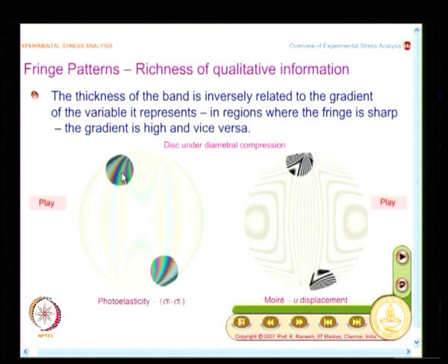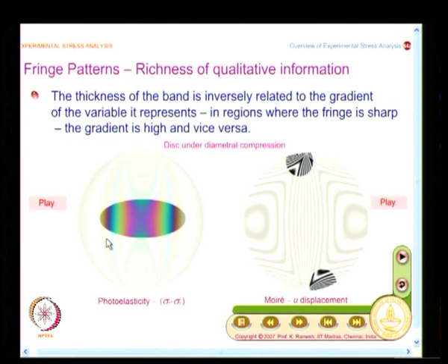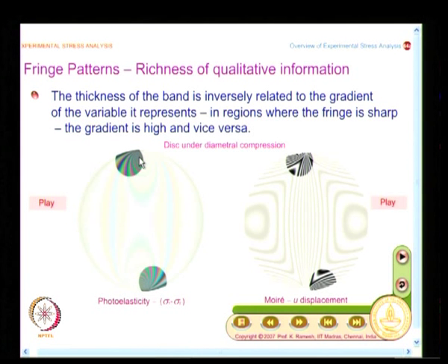This just shows that, to draw your attention, you have these fringe patterns drawn earlier, go back and look at that fringe contour: it is not of the same thickness, the thickness changes, and that is what is tried to be shown in this slide. You have a very broad fringe here. And let me repeat, I have very sharp fringes here, and the same fringe becomes increasing in thickness. So, essentially what you find is that the fringe band is not of constant thickness.